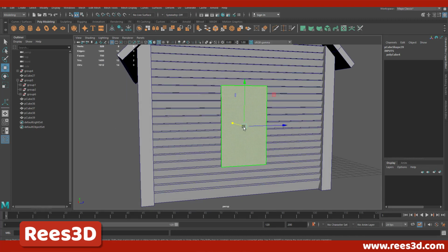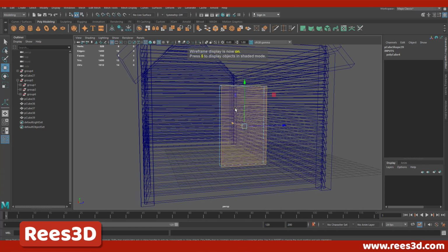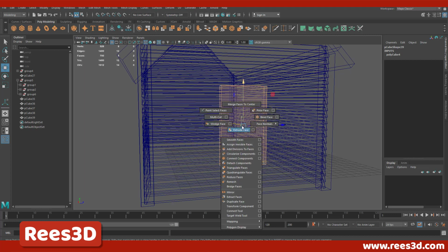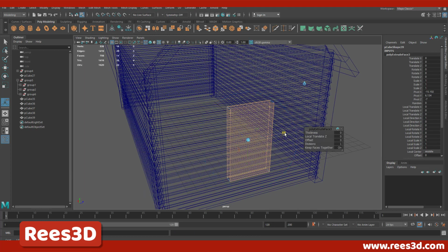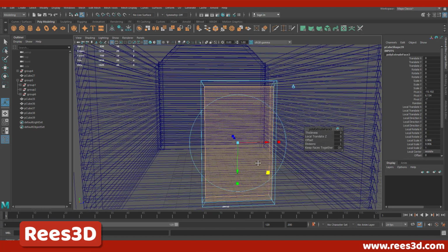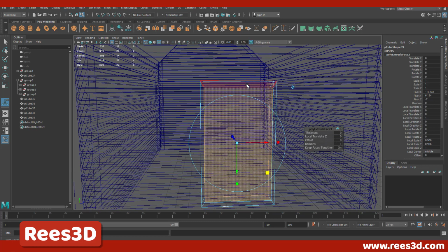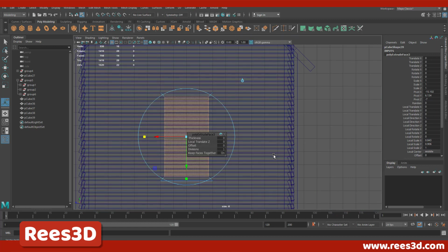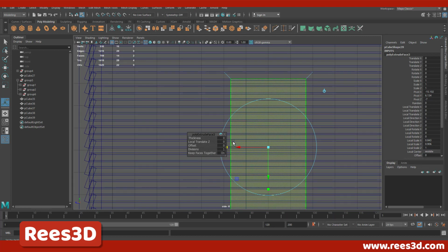Okay, good. So now I'm just going to select these 2 faces. Okay, so the one in the front and the one in the back. I'm going to press shift right click and choose extrude face. And I want to do a scale here, so let's press the scale. And then I want to just pull these guys like so. Now when you do this, because we have a rectangular shape, we will have a little bit longer space here and a little bit shorter space here. So what I can do is I can just simply adjust that a little bit just to match up with the space.